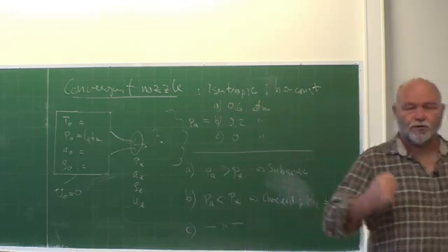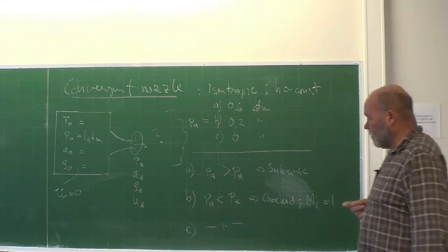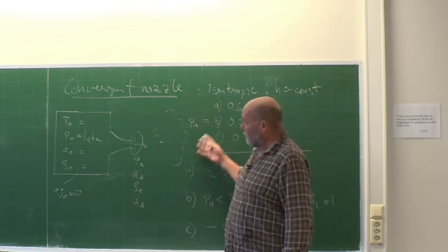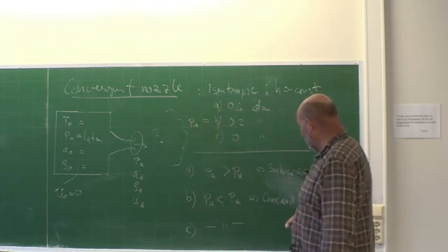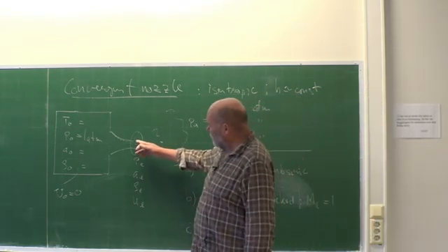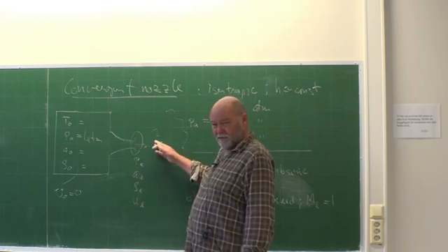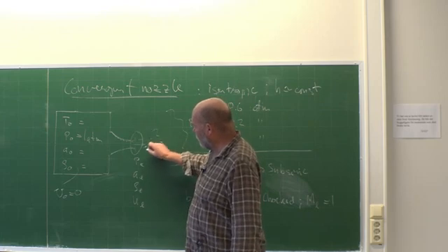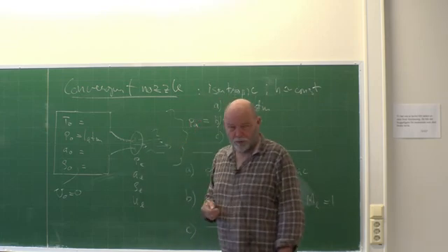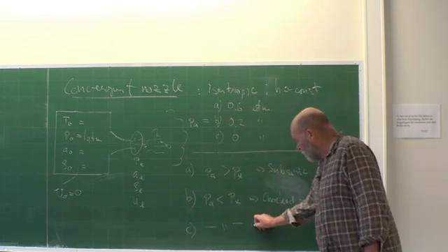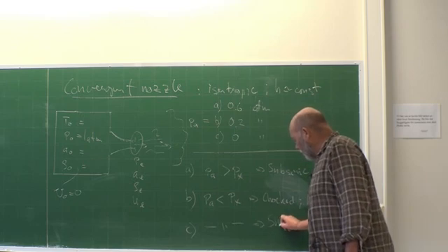Now we will have so strong a driving force, we will establish shock waves for this big reservoir to the right. For this one, we will have Mach 1 here, but nothing else on the other side. Just a jet flowing out, no problem there. But with this one, we are going to get shock waves.